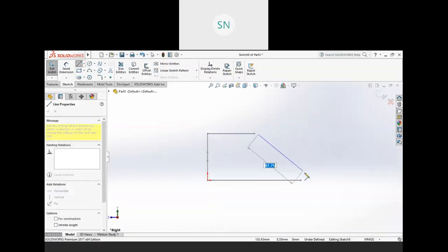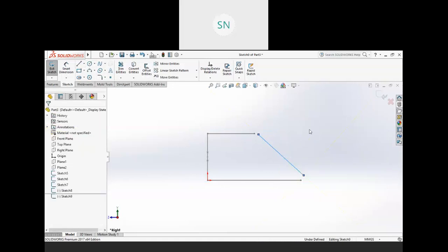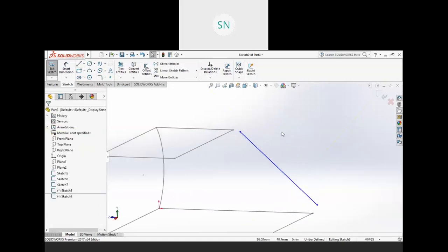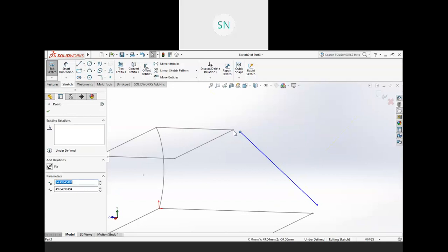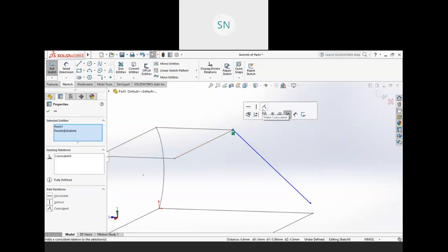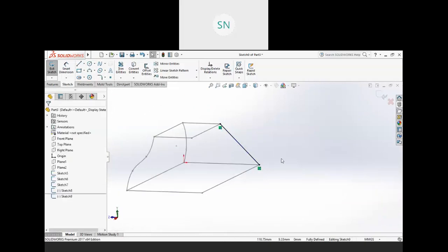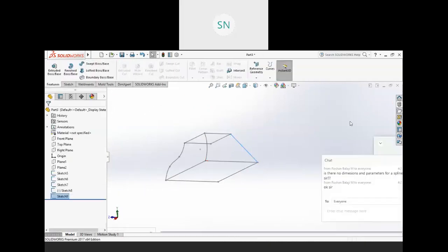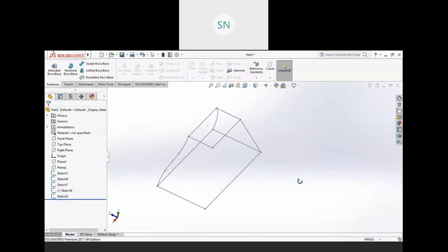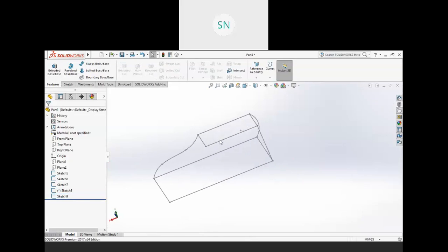So as I told you, create a line or any object at some distance, then connect it manually by yourself. So there is minimum chance of connectivity error, right? Now let me create one more curve, a straight curve from this point to this point.